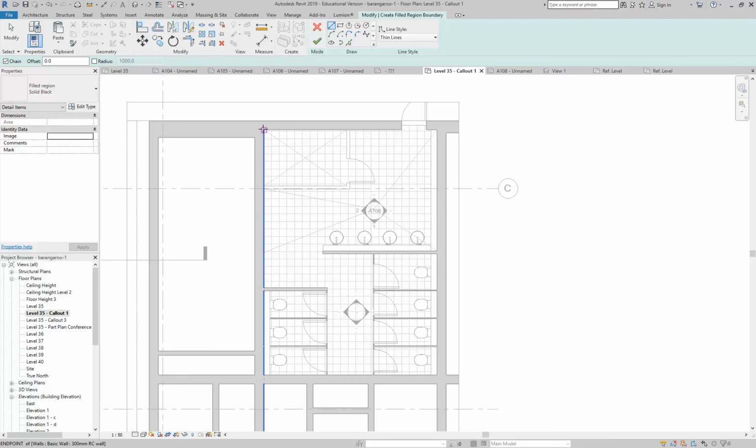You make the floor level, and that's your structural floor, and then your finished floor level is set up above that. That makes you think about when you've got to do your rebates to get the floors flush, or just accept that you're going to have a slight change in floor level from the carpet to the tiles, and you know that because you're modelling it. That's a great approach, and you don't have any of these issues where you've got to assign separate materials and stuff. So that's a good approach.